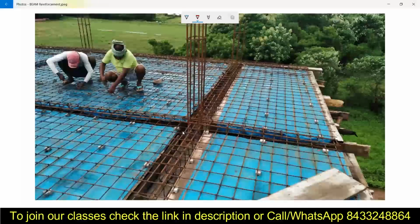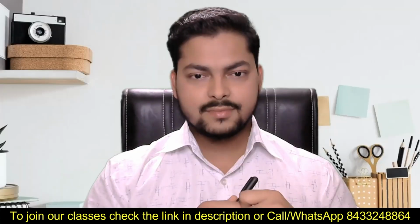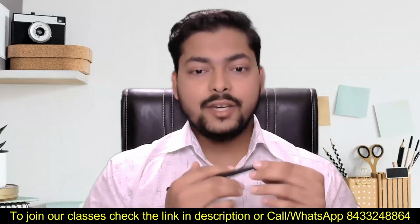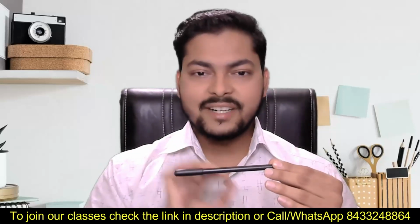Now here you can see some rod binders binding the rods for the slab, and they have already completed the rod binding for the beams. You can see over here, from here to here, we have provided the extra reinforcement at the top. Like this, we have to provide the extra reinforcement. So guys, I think now you have clarified your concept of how the bending moment is generated in the beam and how we provide the extra reinforcement at the ends and in the middle of the beam so that it can counter that bending moment.